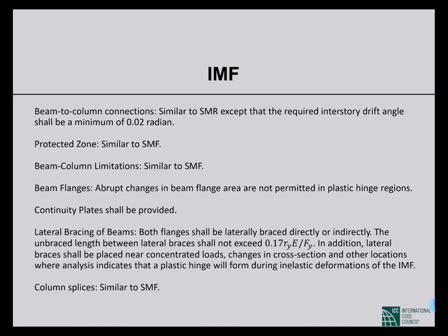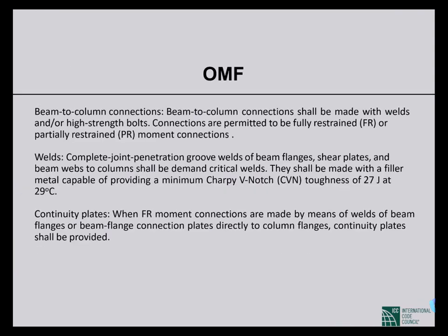But there are some provisions missing in IMF, like provisions related to panel zone. In case of SMF, panel zone design is quite rigorous, but in IMF we don't need to be that rigorous about panel zones. That's related to IMF. Now OMF, beam to column connections.